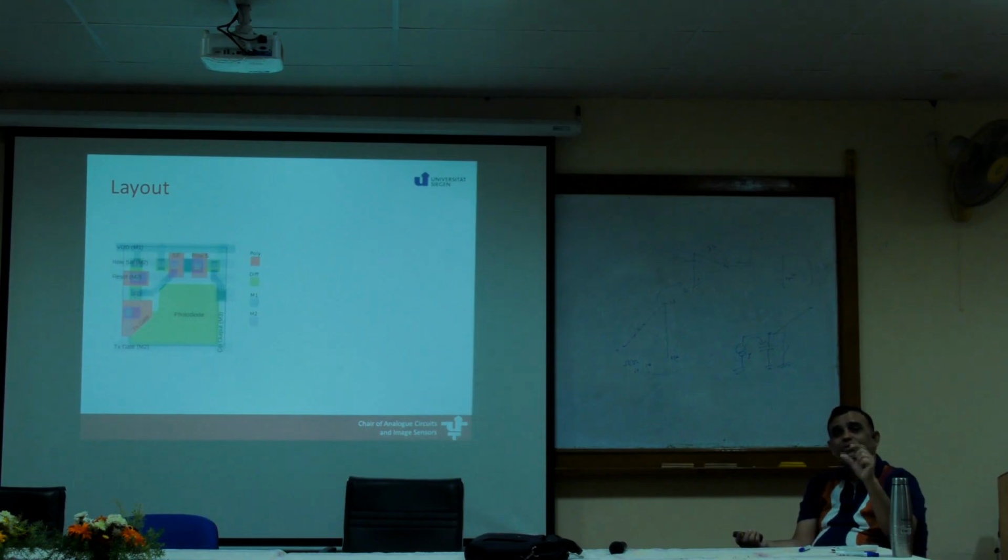So this ratio is called the fill factor of a pixel. What's the sensitive diode area versus what's the total area of the pixel? So an aim of pixel designer is to maximize it as much as possible. And there is a challenge you guys have in your lab. Give me as much of fill factor as possible.